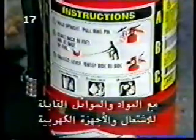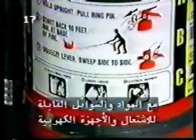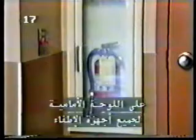The classification and ratings must be clearly marked on the faceplate of all extinguishers. It can be marked with a letter and number, such as this one, or it can be marked with a picture symbol marking, such as this. Be aware the classification can appear anywhere on the faceplate. Look carefully at these 4 extinguishers and determine what type should be used for each fire.